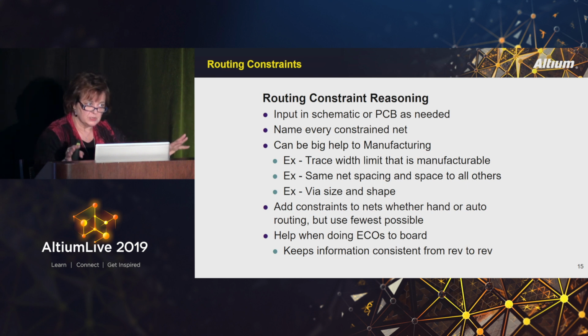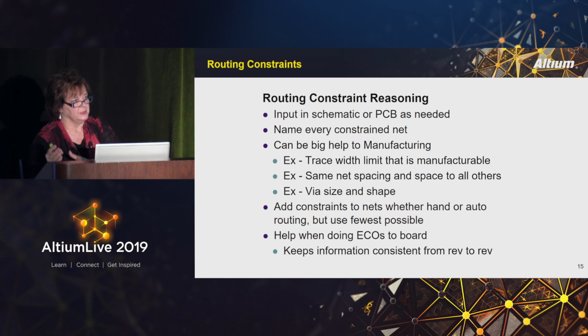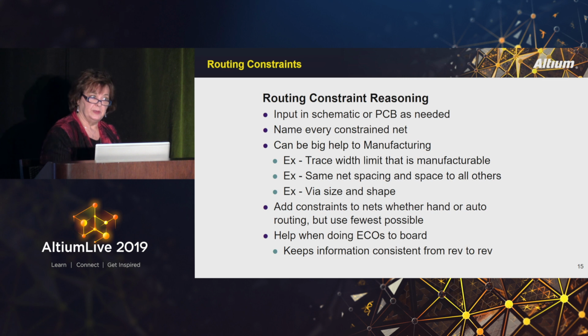So as engineers out there, think about the fact that if you're putting multiple parts or multiple segments on a sheet of a schematic, are you making it easy for the other person to understand that they're going to be near each other, or they're going to be far apart from each other, or whatever? In other words, don't put all the caps on one page. And people do that.